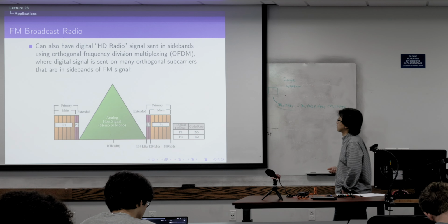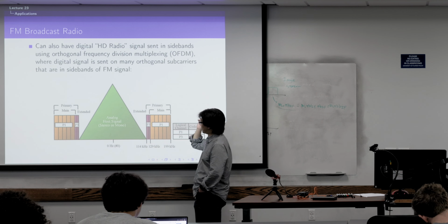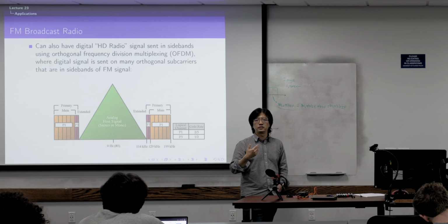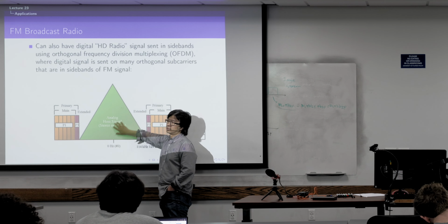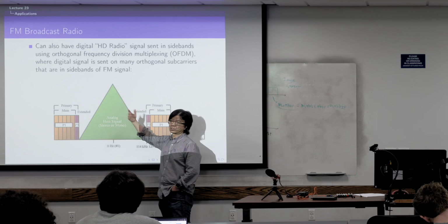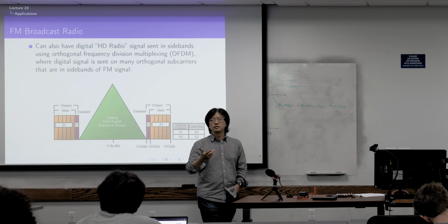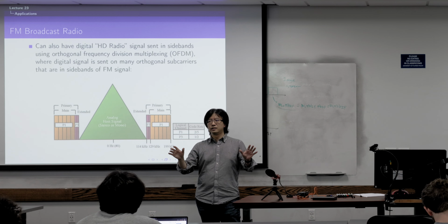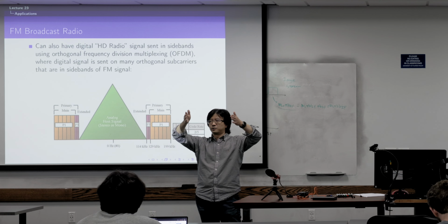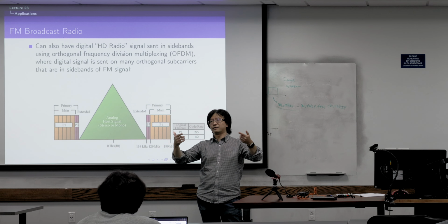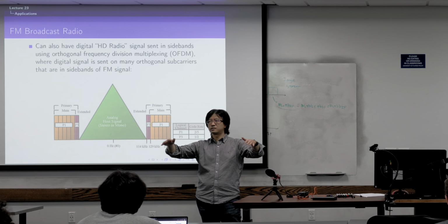Okay, so another interesting thing happening here is that we can mix the analog and the digital communication. So this is our FM signal, what we just saw in the previous slide. But normally when we do the transmission, we need some guard band. The signal is not very clean in frequency. So this is the bandwidth. As we have seen, for the FM signal, it will go on forever, and those are small.